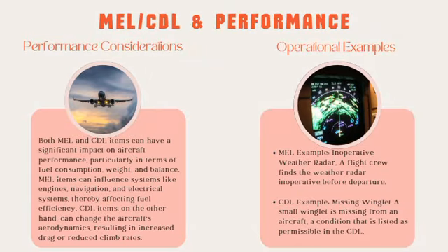Performance considerations. Both MEL and CDL items can have a significant impact on aircraft performance, particularly in terms of fuel consumption, weight, and balance. MEL items can influence systems like engines, navigation, and electrical systems, thereby affecting fuel efficiency. CDL items, on the other hand, can change the aircraft aerodynamics, resulting in increased drag or reduced climb rates.